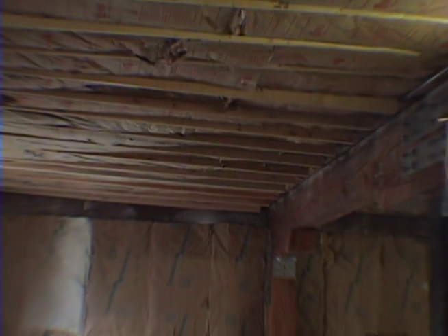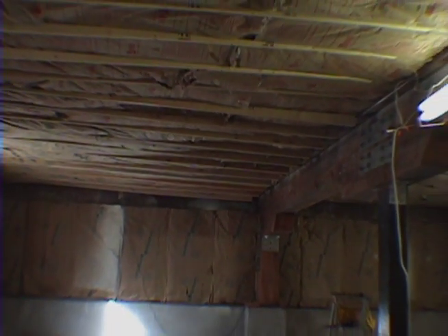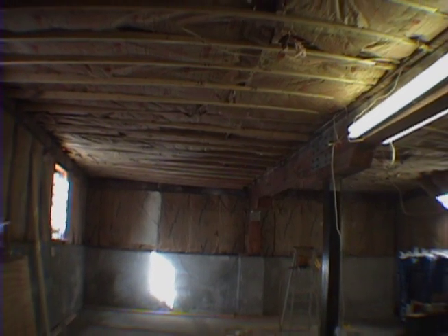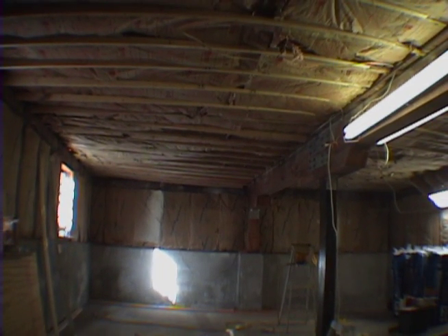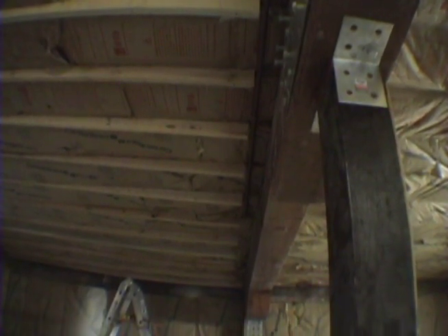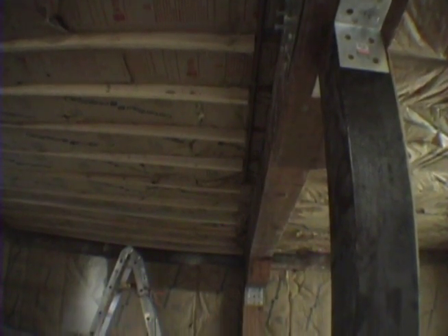When it's all said and done, you can see that we have a nice 1.67 degree angle that will slant the ceiling from the back wall of the control room towards the main support beam for the existing structure. If the water pipe had not been there, I would still want to put some sort of a gap, maybe a 1/4 inch or so, between the angled wood and the main beam to contribute to the decoupling effect.